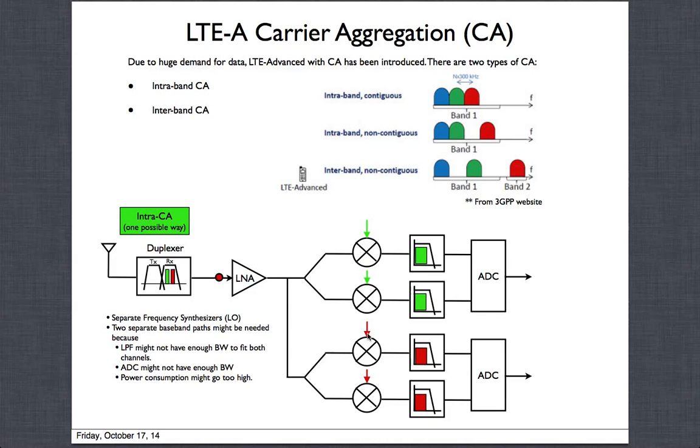So that means a lot of area, a lot of power and all that stuff to support intra-band in this way. It has not increased the number of input pins, so you can still use the same input. So that's a good thing. You can still use the same LNA front end and split the output to do this, but it has doubled other hardware in the circuit, even though it has not increased the number of input pins.